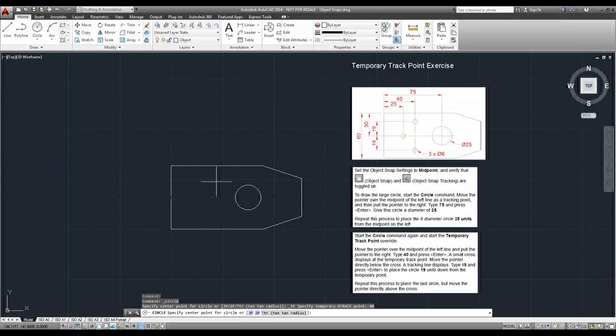Okay, if I want to draw the circle up the top there, again, go close to the tracking point, drag my cursor up. Distance there is 19 mil, so I type in 19, enter, and then it asks me what's my diameter. So I'll go D for diameter. I'll go 6, like that. And it's just a matter of repeating the same process, replacing the other 3. So pretty cool. When I learnt how to do that, I thought that was pretty amazing, so I thought you'd enjoy that one too.